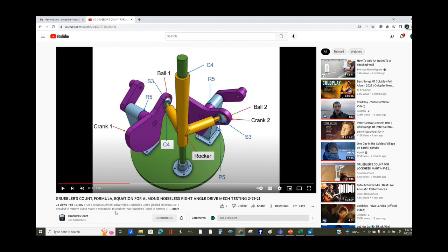Okay, back to the example about the ball table with the 2 THK rails. I used to have to troubleshoot those when they were binding, and I almost always found out that the planar surfaces that the rails mounted to weren't parallel to each other, and they almost always bound up.